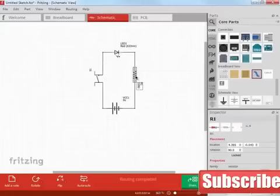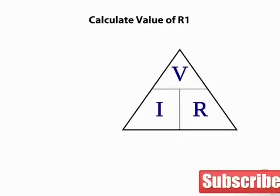And the resistor is the one that we have to select in order to get the proper current flow characteristics through that diode. We had already mentioned we're going to use a super bright LED, which is quite functional at 20 milliamps. So using Ohm's law, the 9-volt battery, we need to calculate the value of the resistance. So calculating the value of R1, we use the familiar Ohm's law. And the version of the equation that we're going to use is R equals V over I.